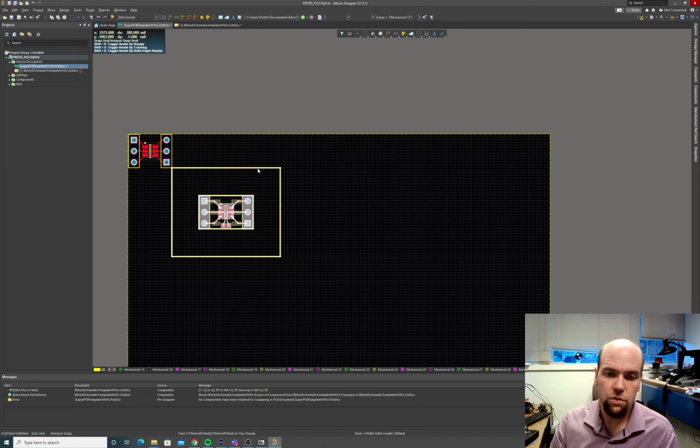So what we could do as we're doing this is keep on adding these. As we add a part, if it's adjacent to another part, we add a 6mm buffer, and it'll allow us to do this. If you want to use a bandsaw, it can be a little bit more narrow. If you have a different tool, a lot of times little cutoff wheels or little tile saws are things people will use. Just remember, this is fiberglass, so you can't just cut it with any old thing. It will wear down most blades, so you want to be a little careful.